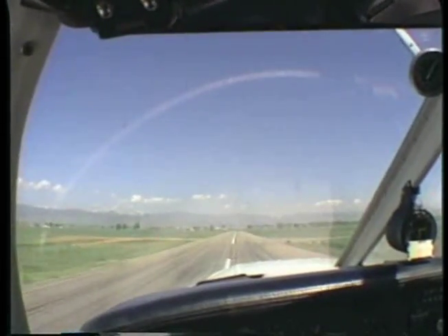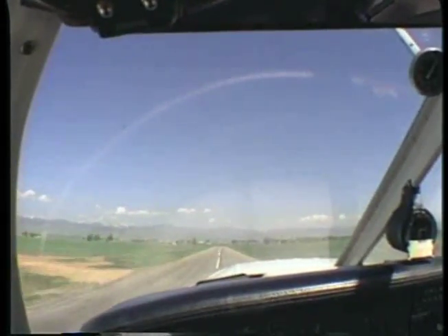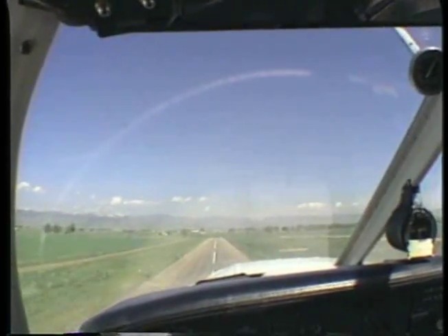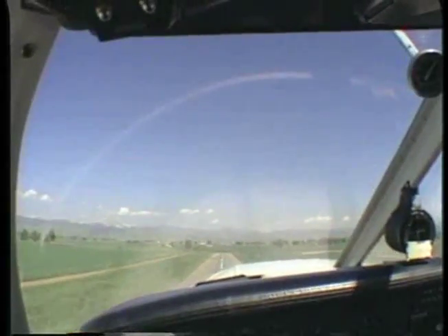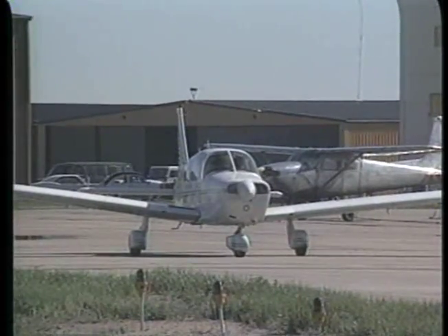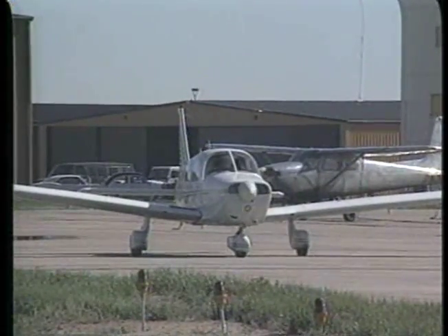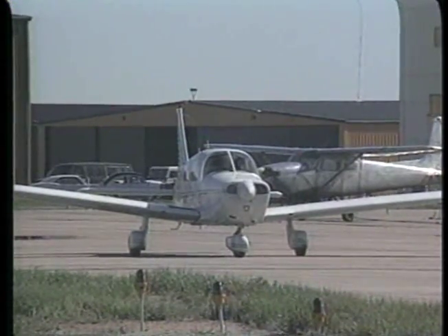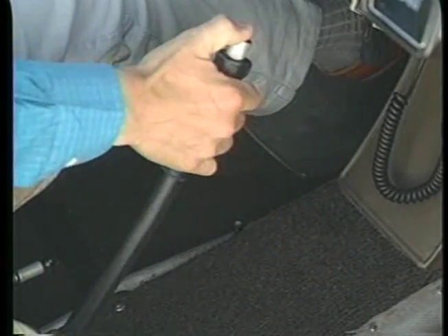Typically, your initial soft field training will take place on a hard surfaced runway. Regardless of the type of practice surface used, soft field techniques are a valuable part of your flight training. If possible, complete your pre-takeoff checklist on a firm surface in an area free from loose sand and gravel. This helps to prevent propeller and airframe damage caused by flying debris. Set the flaps for the maximum performance takeoff as recommended by the manufacturer.